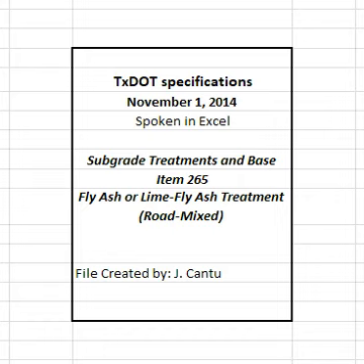Sprinkle the treated material in accordance with Item 204, Sprinkling, or aerate to bring each layer to the moisture content directed. Measure the moisture content of the material in accordance with Tex-115-E or Tex-103-E during compaction daily and report the results the same day to the Engineer, unless otherwise shown on the plans or directed.